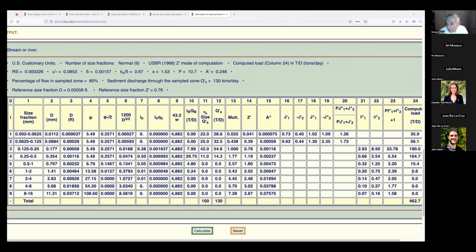I know for a fact that, for instance, in evapotranspiration, the computation of one method vis-a-vis another method could be in error 50% or even more. The Thornthwaite method gives much different answers than the Penman-Monteith, for sure, in most cases that we have tried it. And that's evapotranspiration. And in sediment transport, as I already explained to you, because of the wide range of variability of the variable, which could typically vary 3 orders of magnitude, if not more, we should be a little humble in terms of accepting the accuracy of the computations.